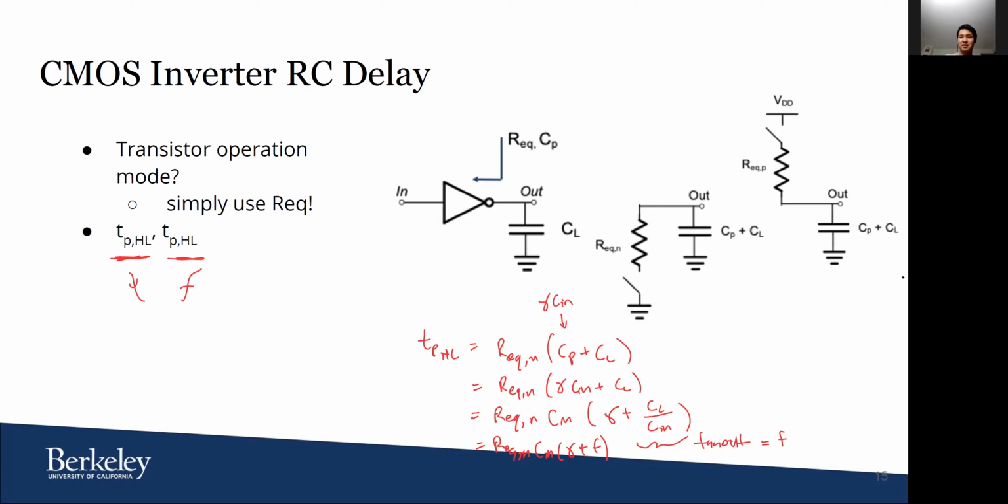Yeah, that's right. It wouldn't be the result of all of them, because that wouldn't make sense; it's not how the circuit works. That's correct. Let's exaggerate this. If you have one inverter and then one big inverter here, the parasitic capacitance is looking in here, and the load capacitance is looking in there. So CL, from the perspective of the small one, would be equal to the C_in of the big one.